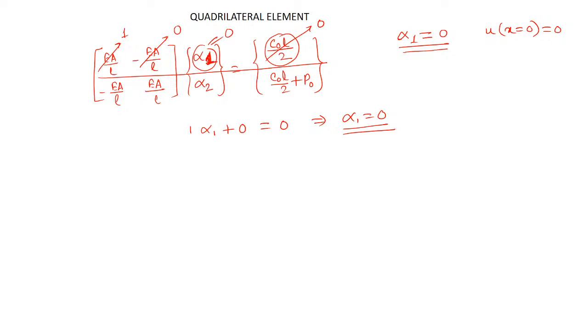We are ensuring that the displacement at that point has the value that has been specified. Whereas the Neumann boundary condition is not so. The Neumann boundary condition appears naturally in the weak form, which is why it is called the natural boundary condition, whereas the displacement boundary condition is called the essential boundary condition. We have to enforce it, so that is why we made the right hand side equal to 0.